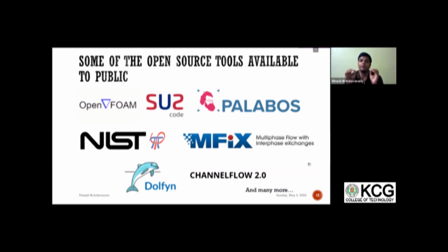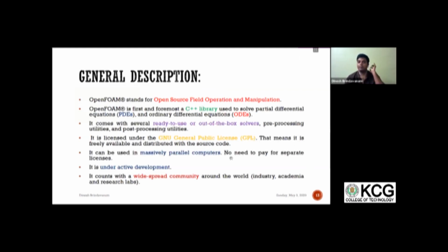Yeah, there is another question on how much mesh size you can use to solve the CFD. There are some slides I'm going to come through, but to give an idea, there is no limitation on the number of cores or mesh you want to use in OpenFOAM. There is no limitation at all. You can use whatever capacity you want. The only problem will be your computational resource, that is, your computer hardware, how much it can handle.